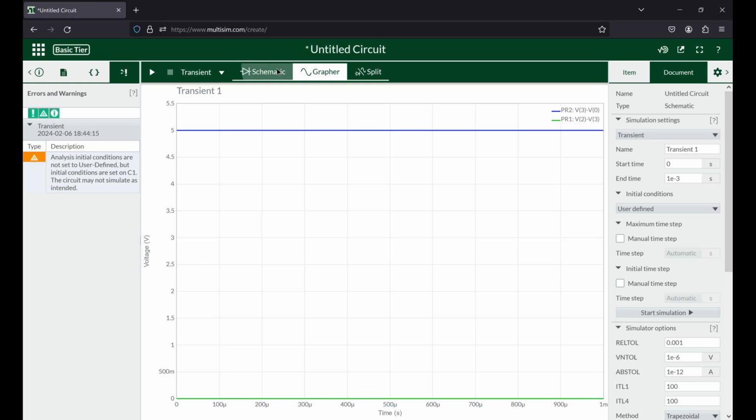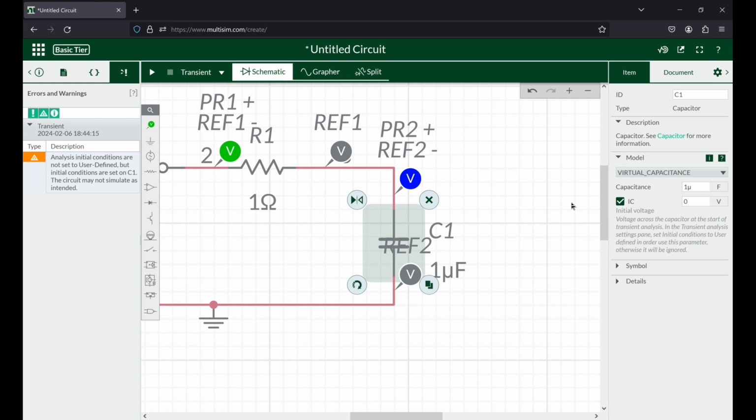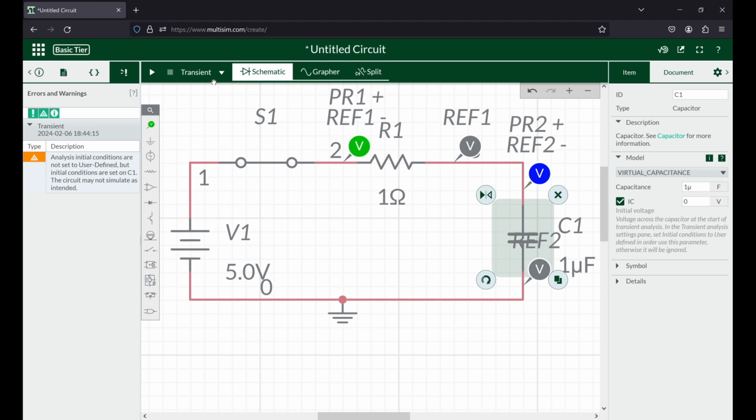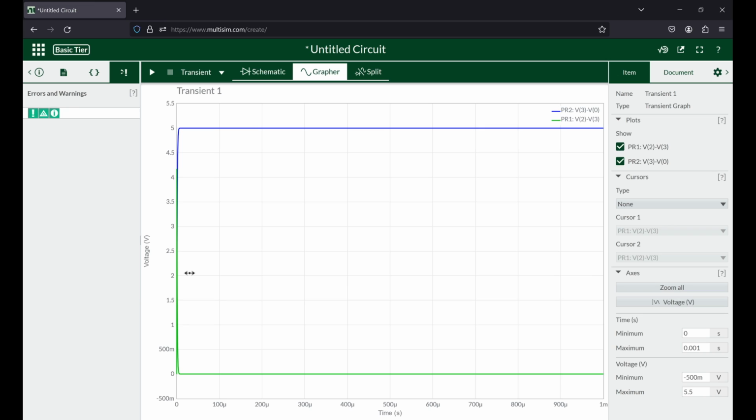and to use my settings, because, for example, I may want to simulate how the capacitor charges with an initial charge already present, right? So instead of 0 volts, I may want 2.5 or something. Or maybe I want to see how it discharges, right? So let's run the transient analysis, right? And now there's something different.